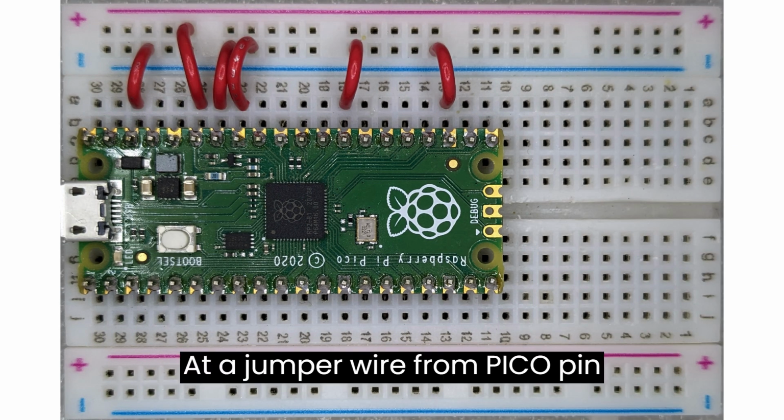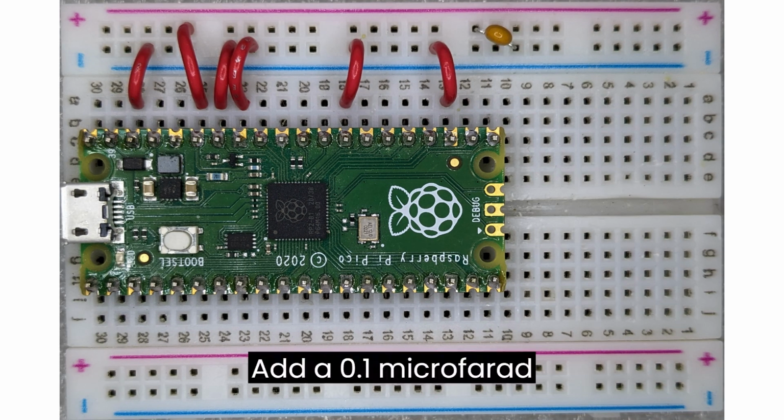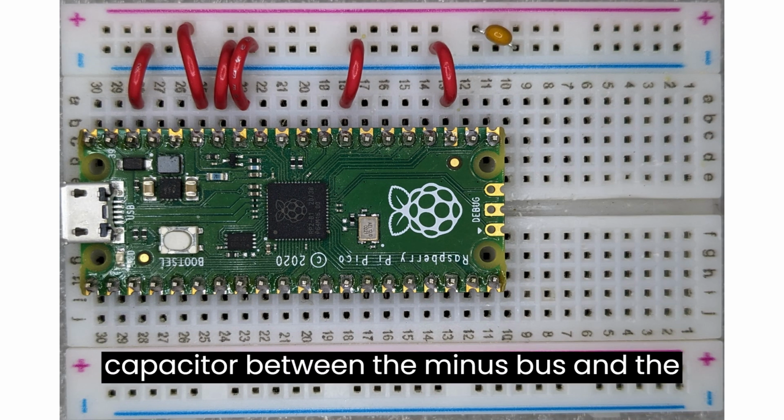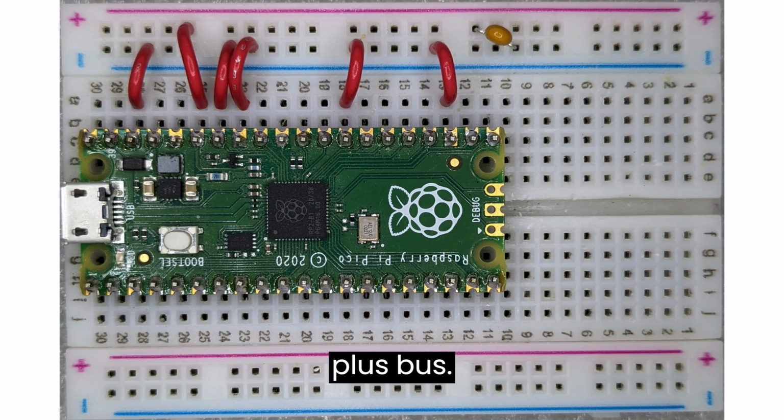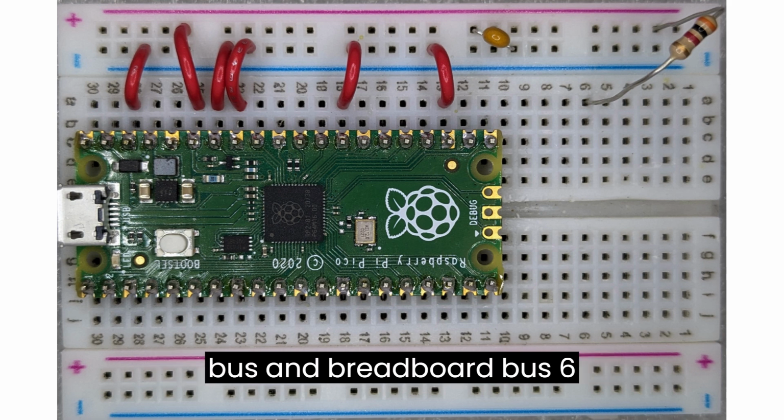Add a jumper wire from Pico pin 35 to the plus bus. Add a 0.1 microfarad capacitor between the minus bus and the plus bus. Add a 3K resistor between the plus bus and breadboard bus 6A.